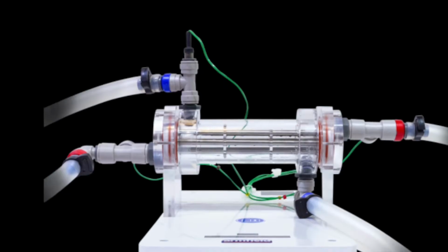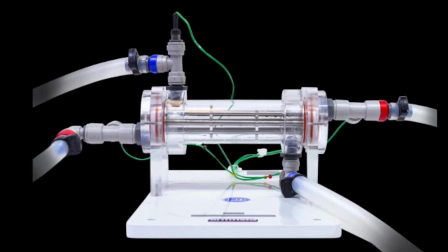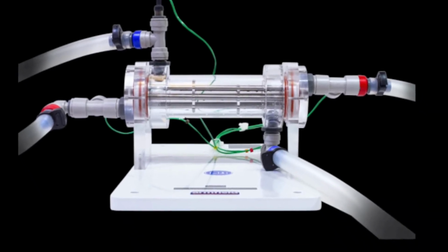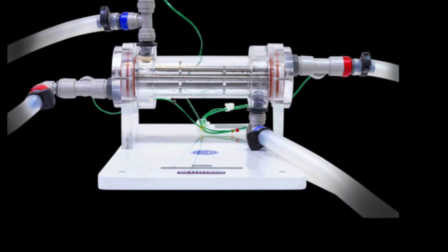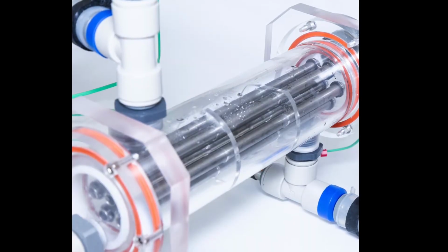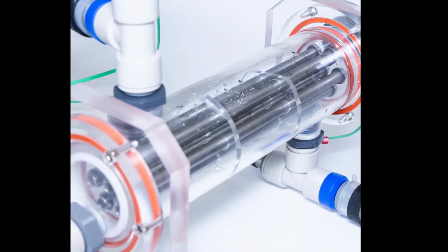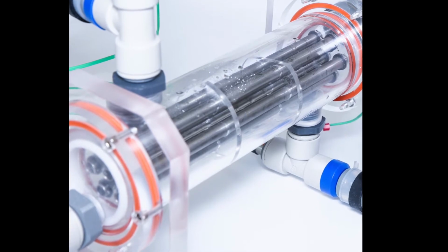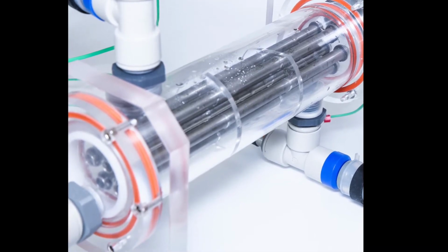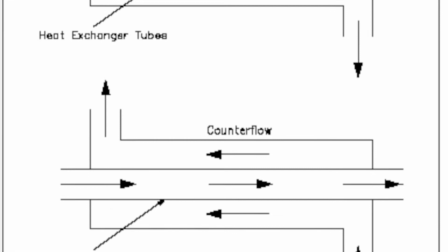Heat exchangers are conventionally used to transfer thermal energy between two or more fluids at different temperatures. A shell and tube exchanger consists of several tubes mounted inside a cylindrical shell in which two fluids can exchange heat. One fluid flows over the outside of the tubes while the second one flows through the tubes. The fluids can be single or two-phase and can flow in a parallel or a cross-counter flow arrangement.